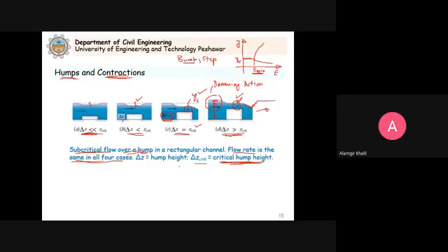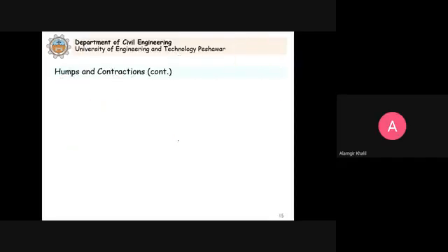So actually in this situation, you will see that this is the hump, that it has a flat top. This becomes a broad crested weir, and this is what you saw. In the broad crested weir, when we operate the gate, we have the critical depth, and before that we have the subcritical depth, and immediately after the gate it was a supercritical depth. So this is what we already observed. We will see this when we solve a problem, and also we will study the broad crested weir in the coming lecture. Clear? The explanation is given in your textbook. You can read about it.